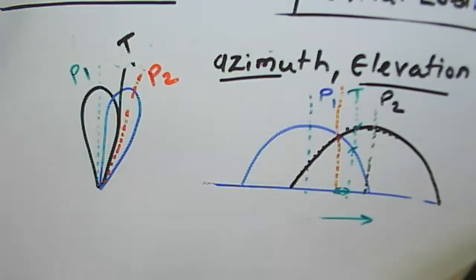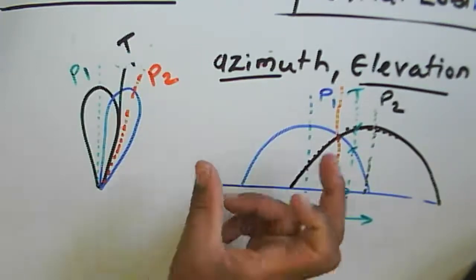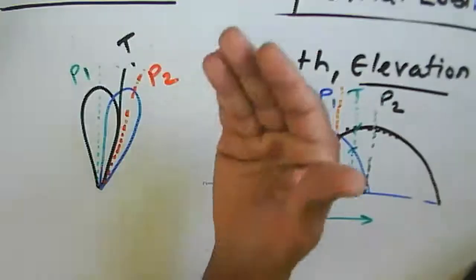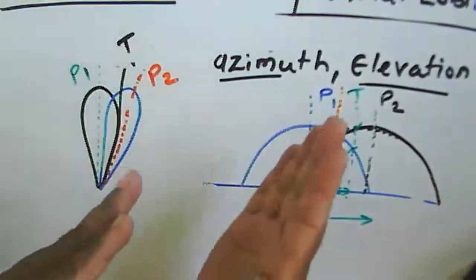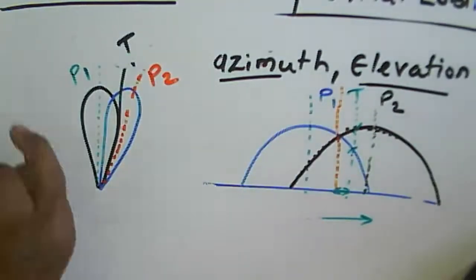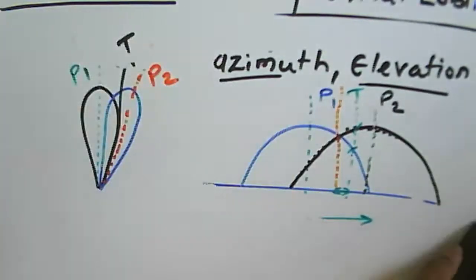and they send a pulse, then these four antennas receive the echo signal, and from the measurement of the amplitude of the echo signal, we can find out the error in terms of azimuth and elevation, that is, the angle error, whether it will be up or down, or we can find out the range. Similarly, using sequential lobing or a conical scan method, we can find out the range as well as the azimuth and the elevation.